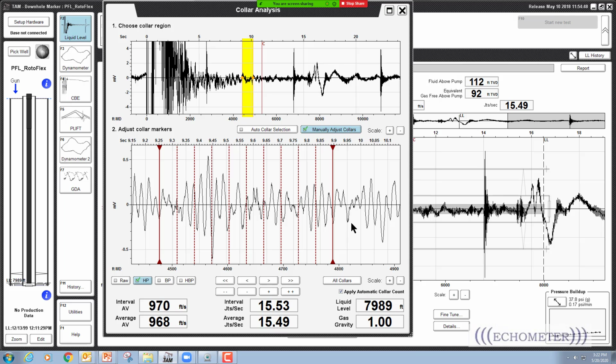My guess is that the velocity isn't that significant, because the acoustic velocity in gas is on the order of 1,000 to 1,500 feet per second, and the gas velocity of travel is probably not that fast relative to the acoustic velocity. Okay. But if you have some data that shows otherwise, I'd like to see it.